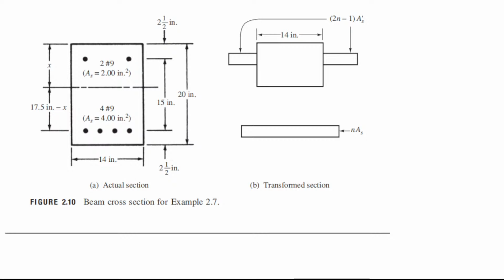We have to convert that area of steel to an equivalent concrete area. What are we going to do? We know, because last meeting we multiplied that steel area by the modular ratio. So n times As, or nAs. That is for the tension side or the bottom bars.